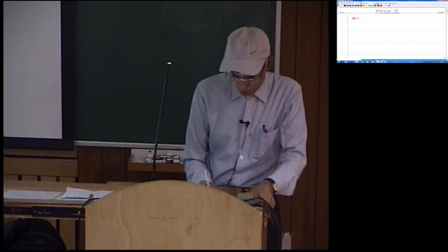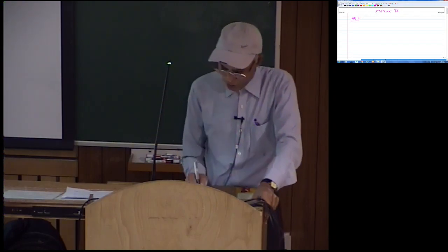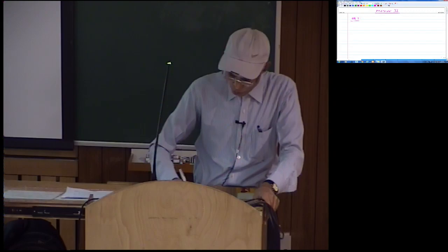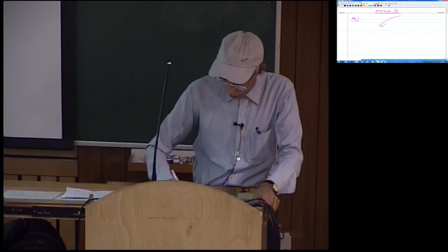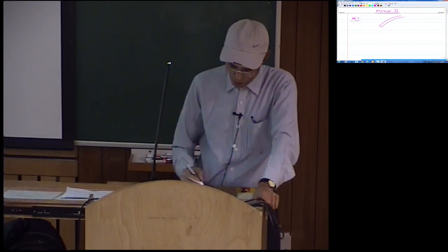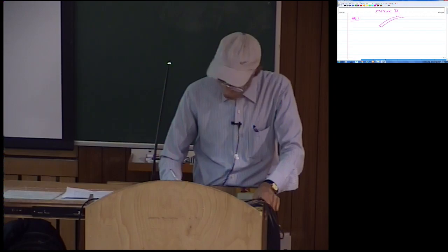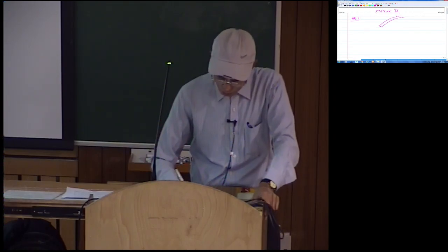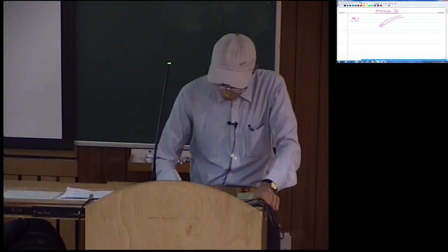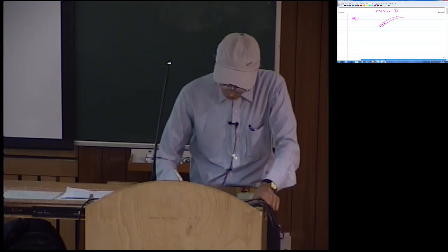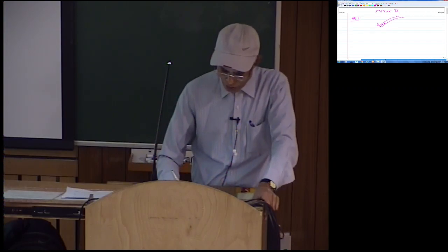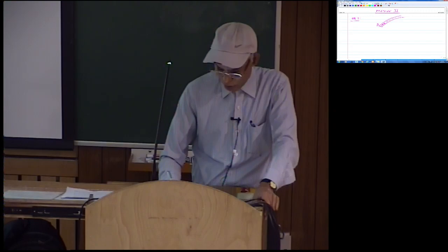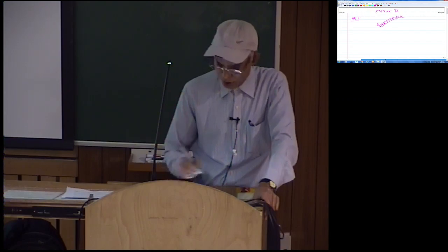Question 1 was actually on locking. So what I had said was that a curved beam element can of course also be modeled using straight elements. Suppose you have a curved beam structure like this. Although it is not necessary to solve the problem, a curvilinear coordinate is taken. Say this is x and normal to this is z, where x at any given point is tangent to the centroidal axis of the beam. So here x would be like this, and here x is going to be tangent like that.